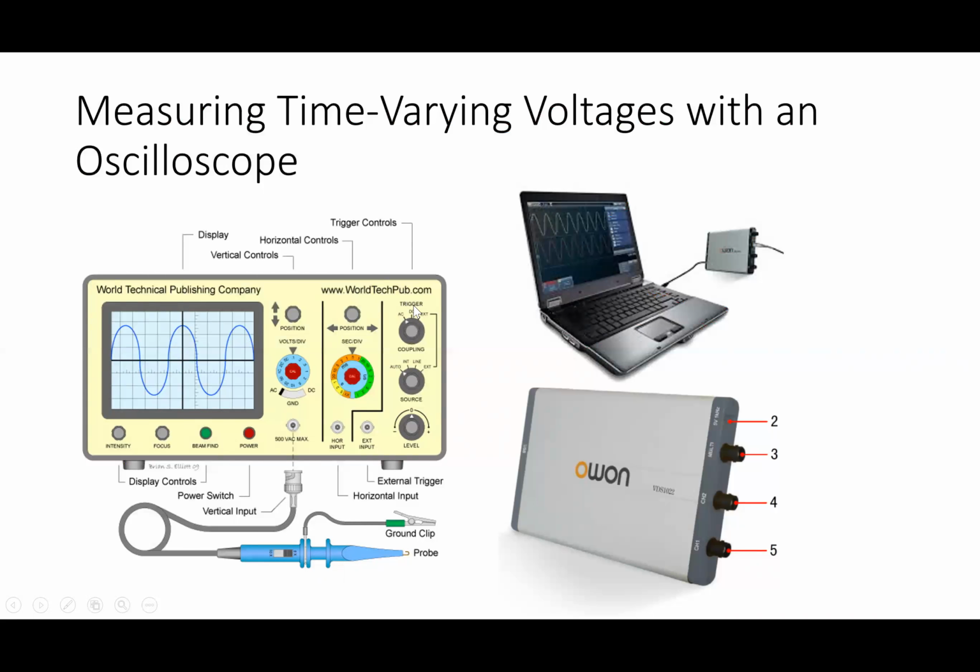All of this circuitry here is to make sure that the waveform always starts on the screen at the same position, so it doesn't jitter around as you sample it at various random times, but rather always starts at the same point. That's called the trigger.